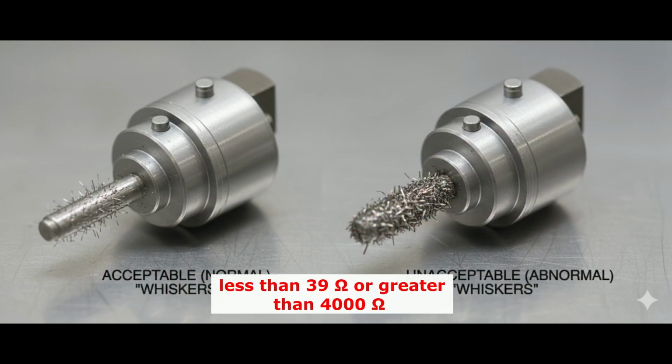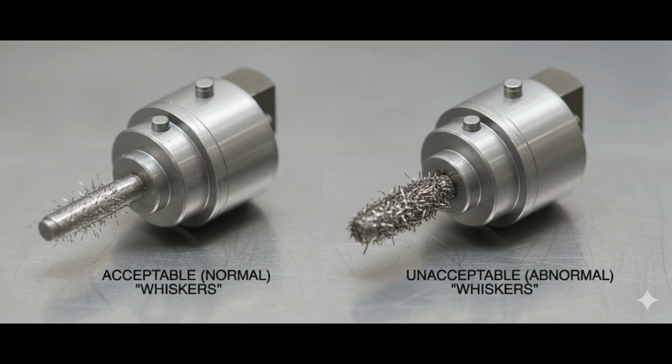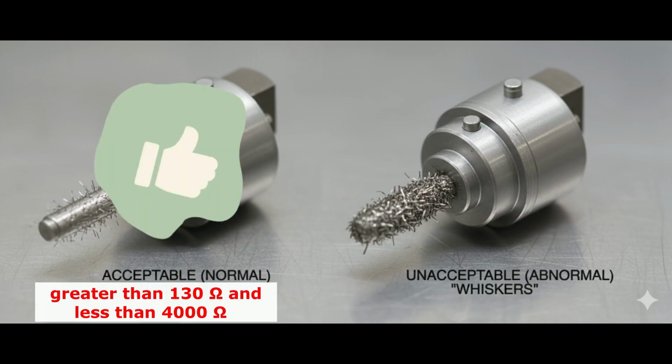Below 39 ohms or above 4000 ohm system fault. Values in these ranges indicate an electrical system failure, such as a short circuit, an open circuit, broken wire, or a missing sensor. 130 ohms to 4000 ohms normal operation. Resistance values within this range indicate that no significant ferrous particles have been detected by the DMS.